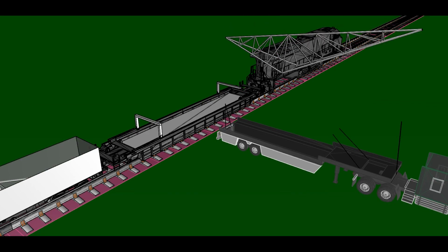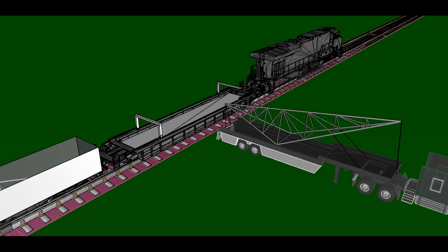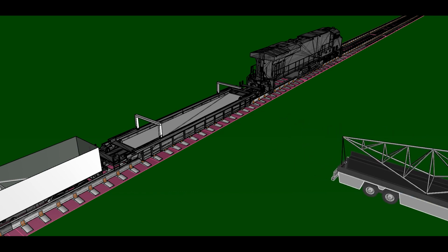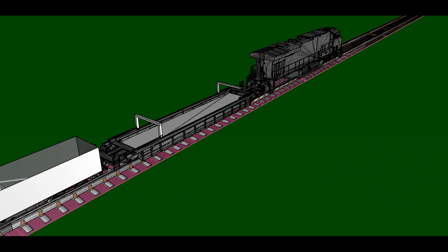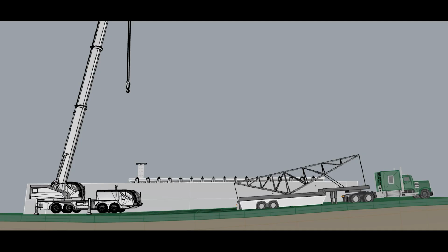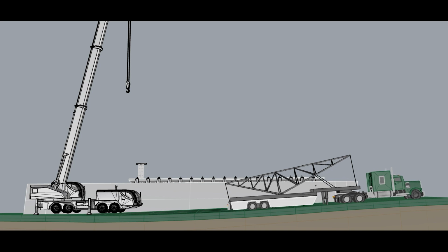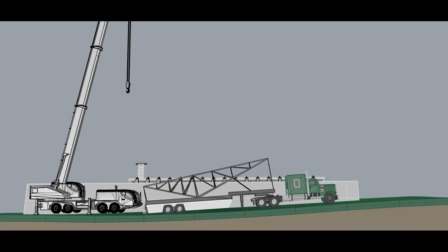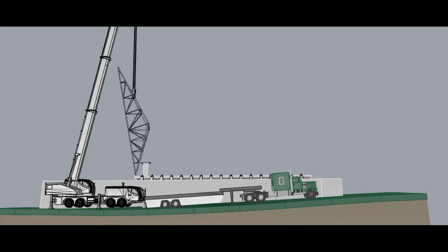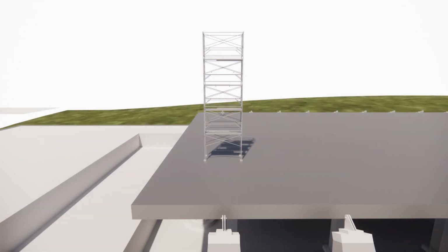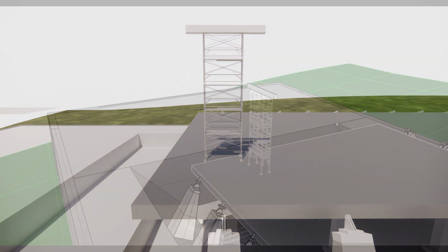The logistics of road transport were carefully coordinated to avoid any disruptions and to comply with road safety regulations, considering the oversized nature of the loads. Upon arrival at the site, cranes were used to lift and accurately place each tetrahedron. Temporary supports were installed and beams to be connected at the ends of the modules were put in place.